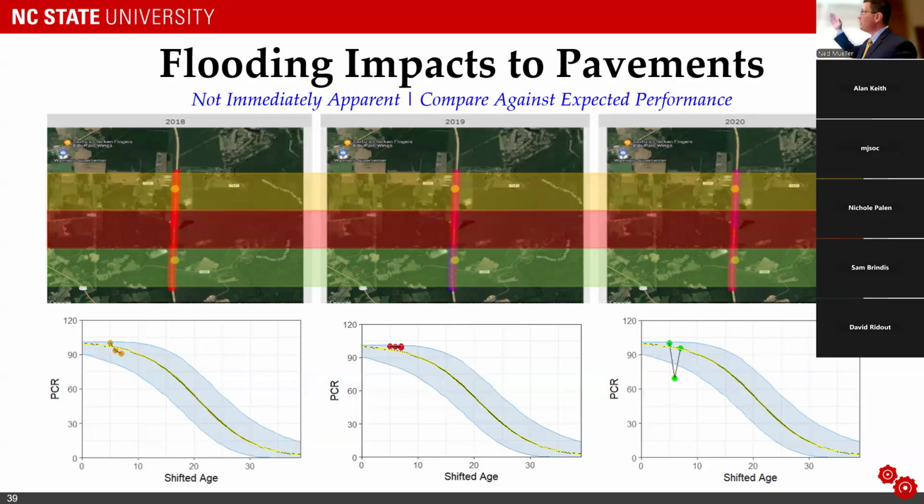If we look at the eastern branch, the yellow color here, it was at that 98th percentile, but then after the storm, it fell below the 50th percentile. So are there pavements at its age that look the same as this does after the flood? Yeah. But it's odd to see a pavement go from really well performing to now being less than average in the location. And then when we look at the far easterly section, you can see that the year after the flood, it actually had deteriorated quite a bit. Turns out that there was a rehabilitation done in the year.